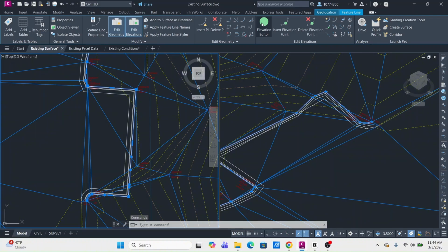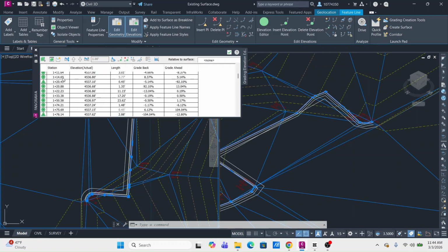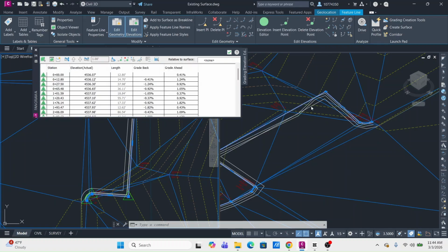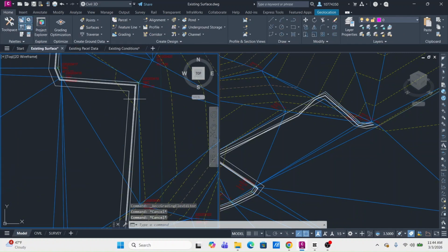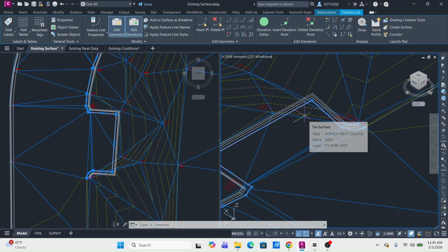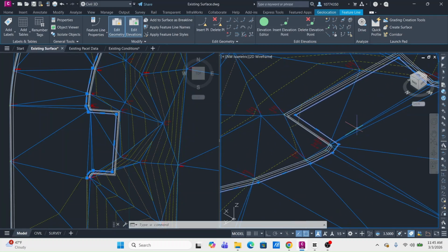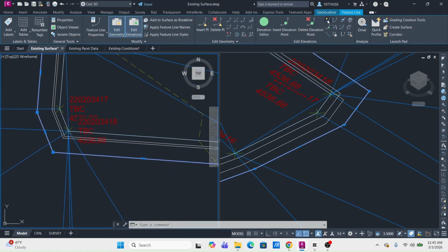So what I'm going to do is go to elevation editor. It has some increments or intervals that it's put into here. So if I just click the top, click the bottom of this, click this delete key, that'll delete all my increments. Now just straighten that line out. And now I'm going to straighten all of these by doing the same thing. Okay, I've straightened all these out. The thing I want to change here, so you can see how these start to level out. I think looking at these elevations, you go over to this lightning bolt over here, do quick elevation.